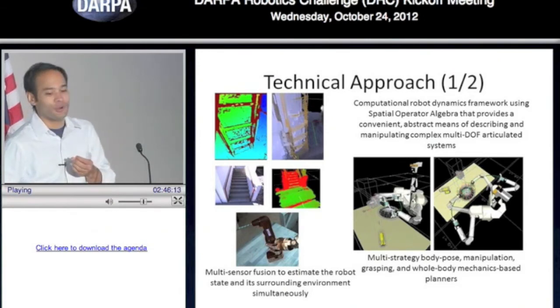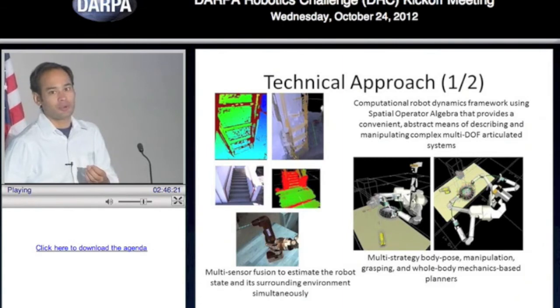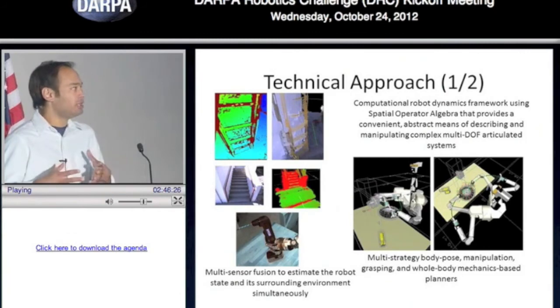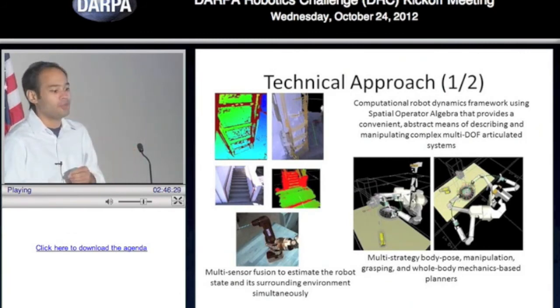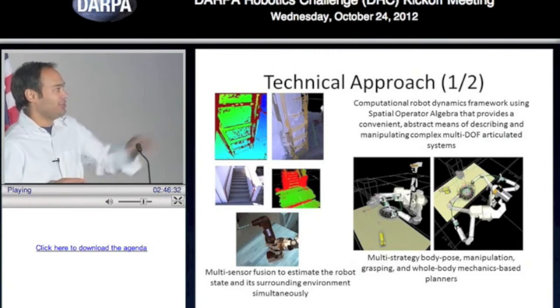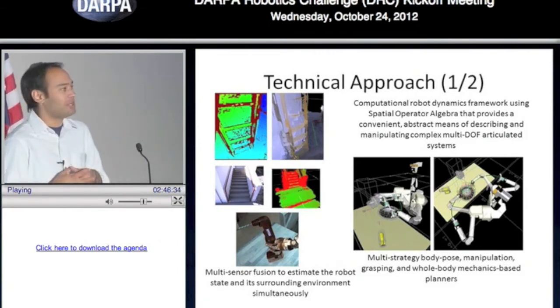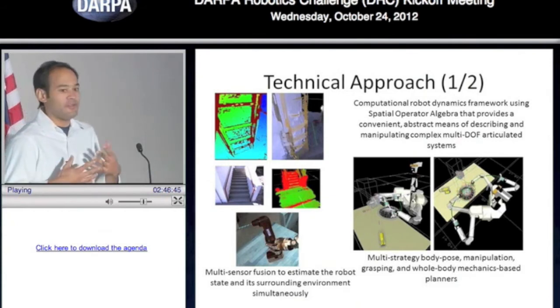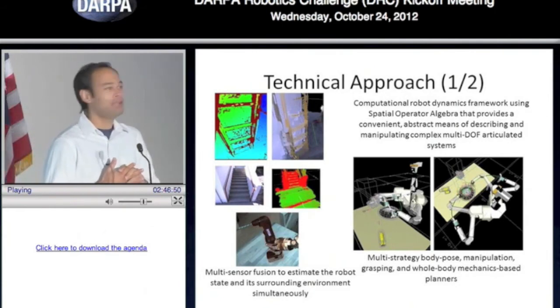In addition, as part of the RMS program, JPL and Caltech have been developing a multi-strategy approach to manipulation planning, as well as grasp planning, and then we combine that with a single-arm collision-free and dual-arm kinematically constrained motion planner that you see in the lower right. Underlying all of this technology is our own mechanics modeling infrastructure that allows us to do kinematics and dynamics both faster than real time for onboard systems, as well as at higher fidelity to do full and complete simulations of the system. Go on to the next slide.